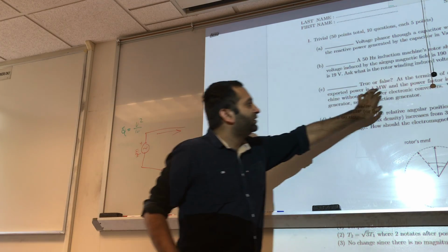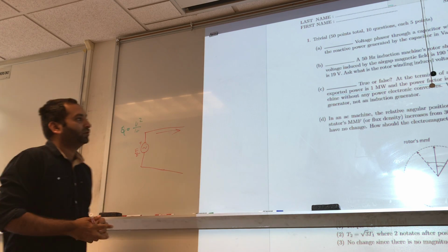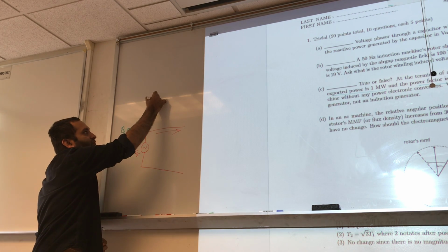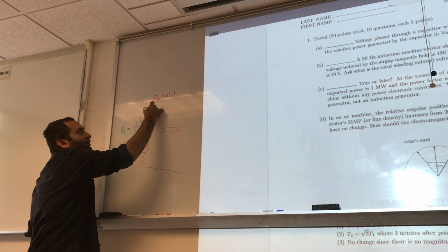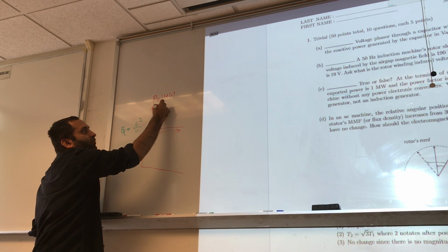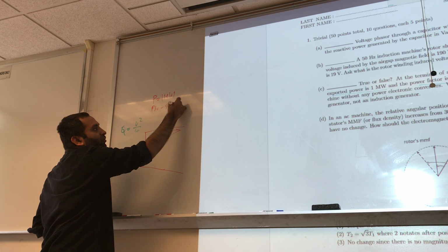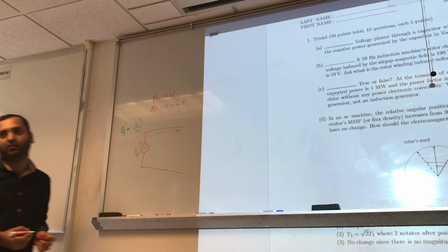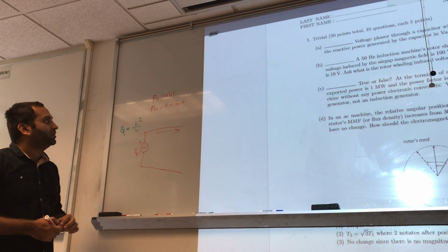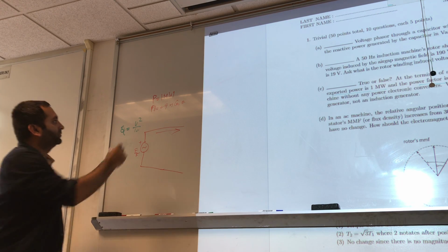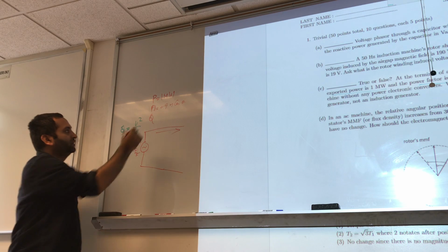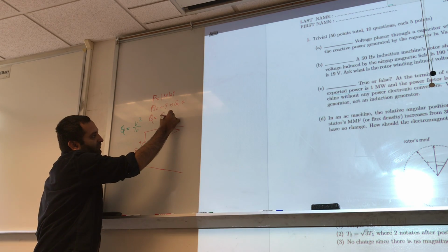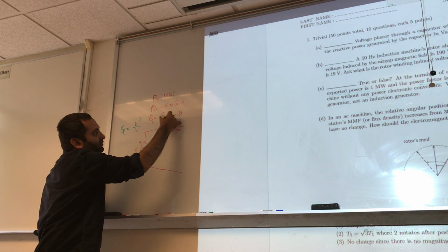And now let's find the reactive power for this. So it's given P equals 1 megawatt and power factor is 0.9, which equals cos theta, right? Power factor is cos theta. So how do you find the reactive power Q? Q equals S sin theta.